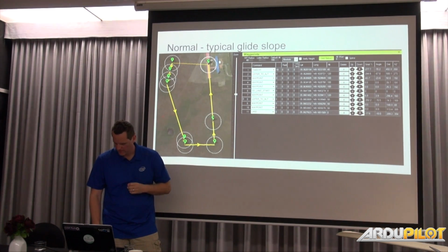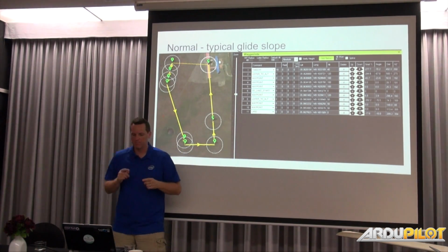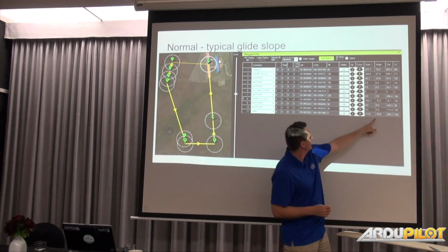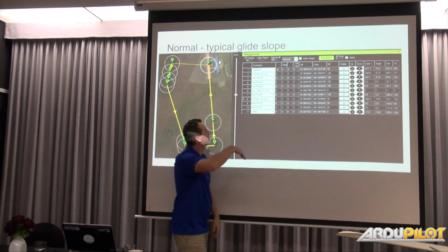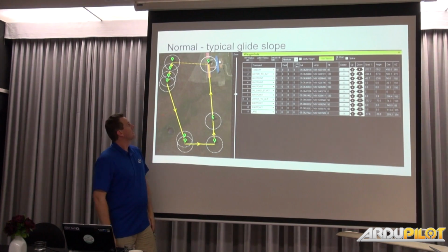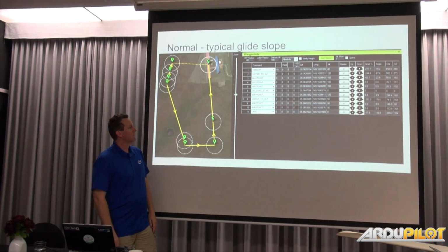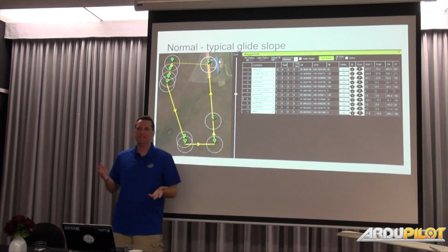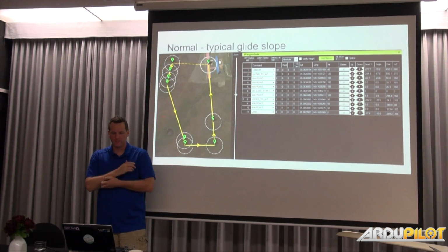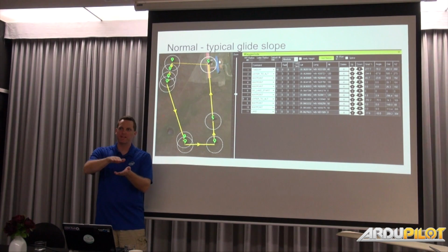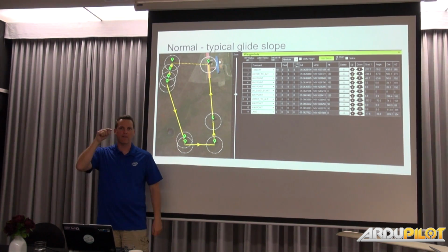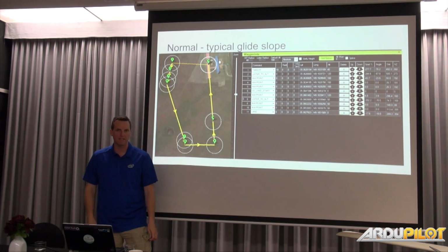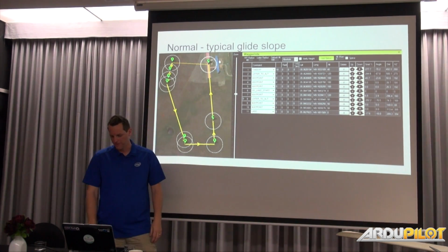Anyways, between points 10 and 11, you can see here, for example, I have minus 10 degrees. That's a common thing for lightweight foam planes. So the lower the number, the better. It's easier on the controller. Usually, if it's too shallow, you can actually give it throttle to maintain a speed. Once you hit that number too high, then turn the throttle off. If it's going down, just speed up, speed up, speed up. So that's what the whole glide slope test is for.